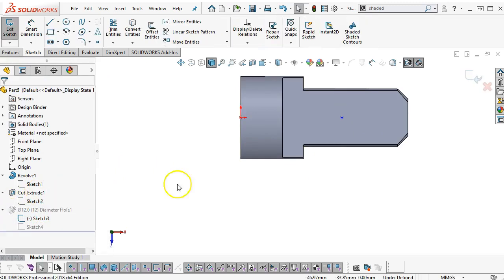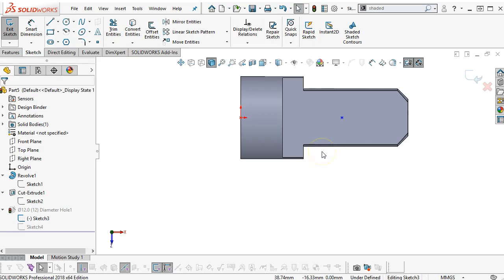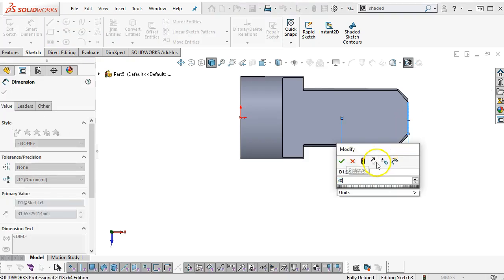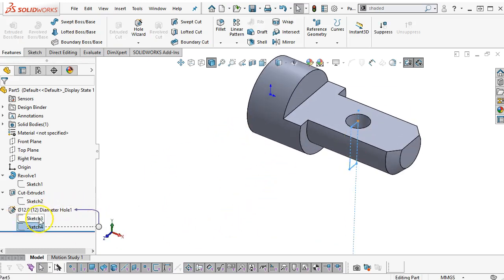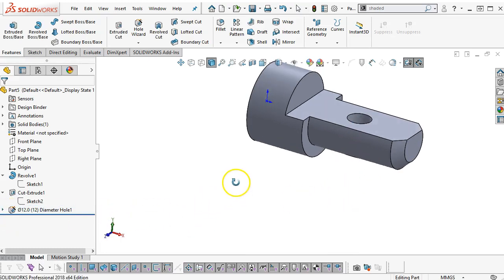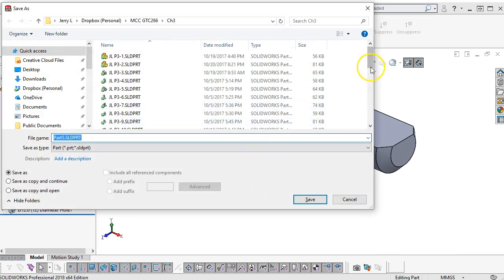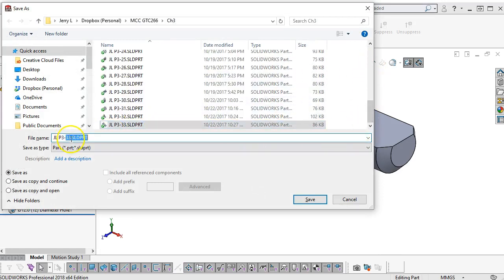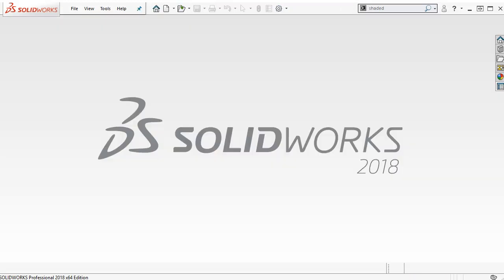Keep in mind that you can edit the location just by editing the sketch without getting back into the geometry. We'll say that that is okay as a correcting or adding dimensions to the geometry. Go minimal on the profile. The second sketch has that profile geometry, and editing it can create additional problems. So first sketch okay, second sketch not so okay. Alright, so 34. Save.